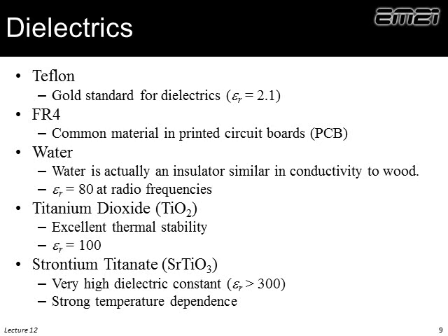I also mentioned titanium dioxide and strontium titanate. These are commonly available in powder form and often used to backfill parts to provide a high dielectric constant. The claims are that they have a very high dielectric constant, on the order of 100 to 300. We have yet to measure that in the lab to confirm it, but that's the claim.